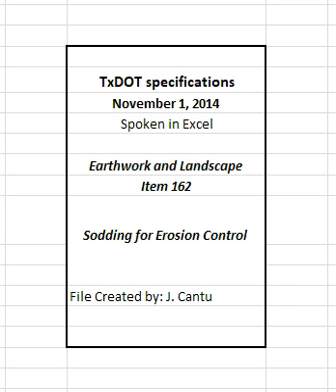Use grass sod with a healthy root system and dense matted roots throughout the soil of the sod for a minimum thickness of 1 inch. Do not use sod from areas where the grass is thinned out. Keep sod material moist from the time it is dug until it is planted. Grass sod with dried roots is unacceptable.